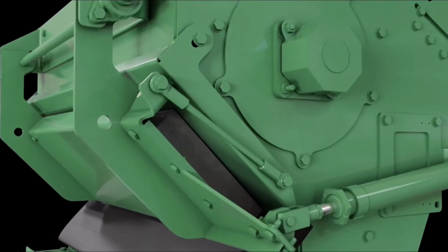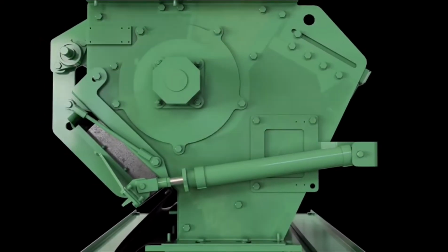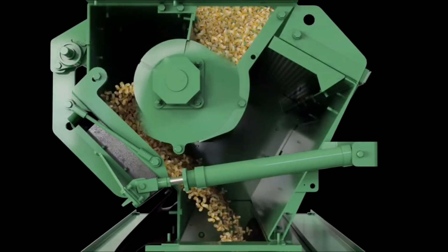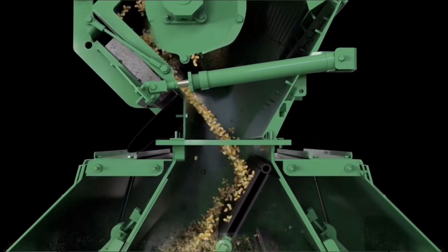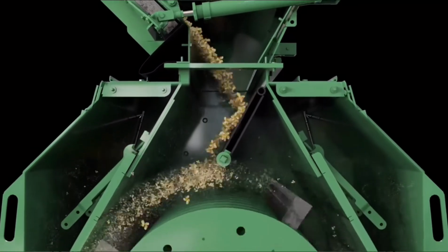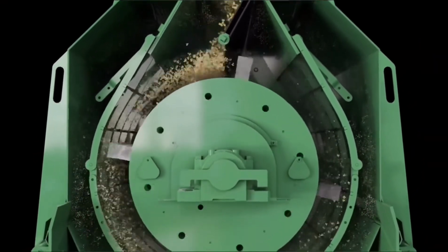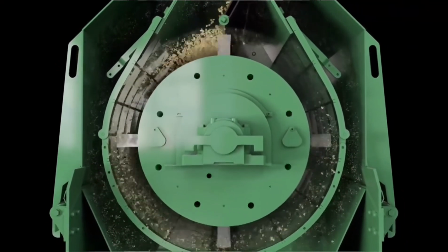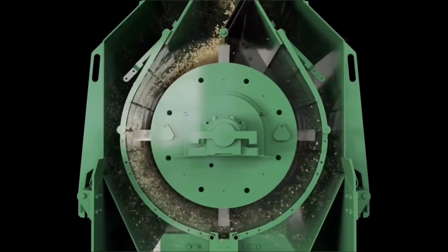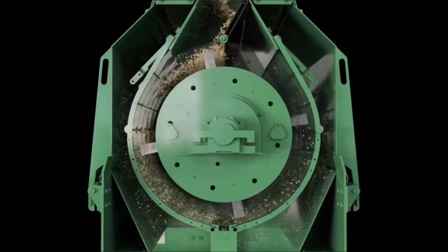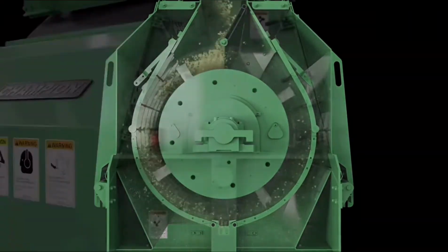There are usually 4 or more series of hammers hinged on a central shaft and enclosed within a rigid metal case. Hammer mills operate on the impact principle between the hammer and the particle to be reduced in size. In a hammer mill, the material to be milled is struck by these rectangular pieces of hardened steel, which rotate at high speed inside the chamber. This radially swinging hammer moves at a high angular velocity, causing brittle fracture of the feed material.